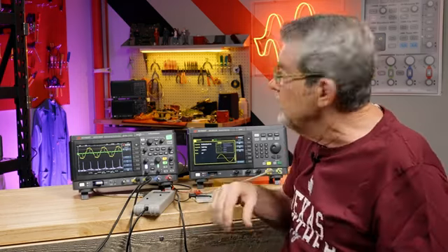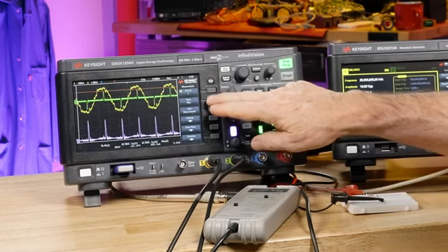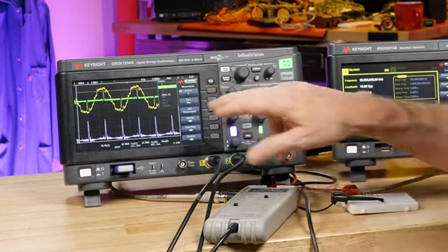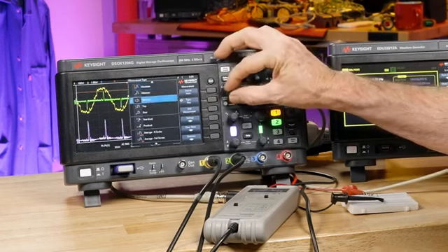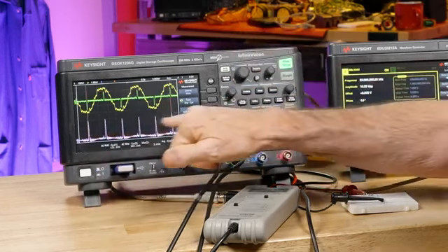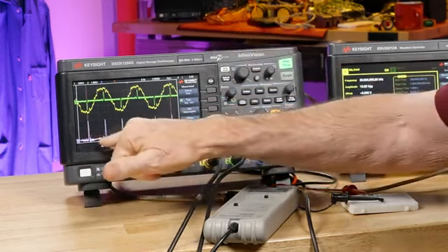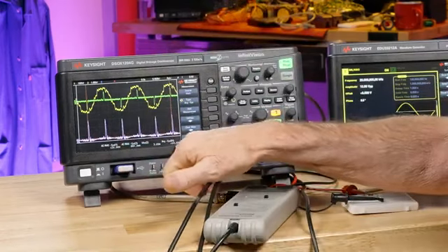So how much power is it consuming on average? For that, let's go into the measure menu and then change the source to math and select average in cycles. So we'll measure the average power, and often the power just goes to nearly zero and then it's pulse. But the average power is about 14 watts. Remember I said the apparent power was about 43 volt amps.